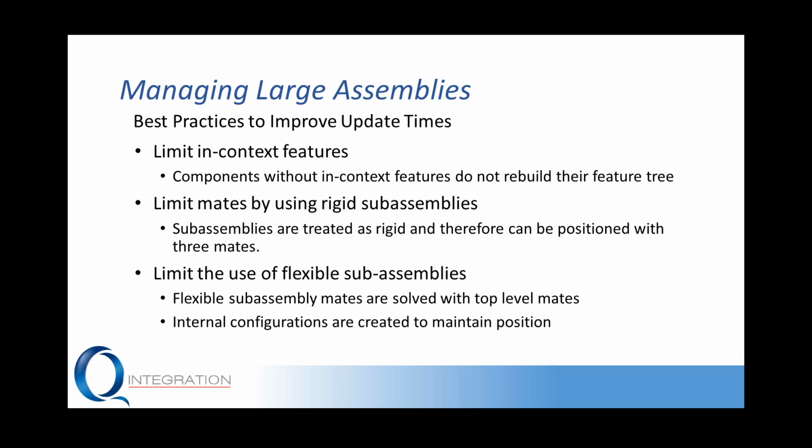This is why if you have an assembly that you bring into your top level assembly and that sub-assembly has movement, we don't see that movement immediately. It's because SolidWorks is treating that as rigid. It is keeping the mates at that sub-assembly level. Now the opposite to that is to make it flexible. So we have that movement at the top level. And what this does is it brings the mates in that sub-assembly and solves them with the top level mates. So we're just adding to the amount of information that needs to be updated each time.